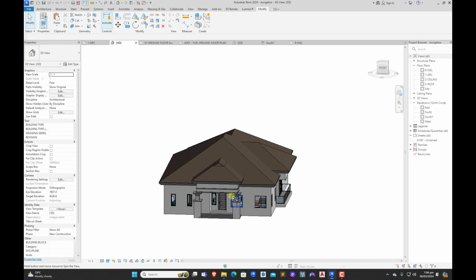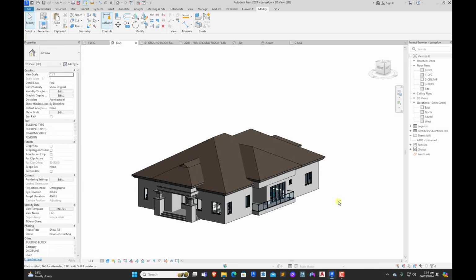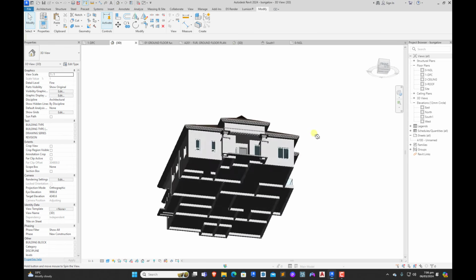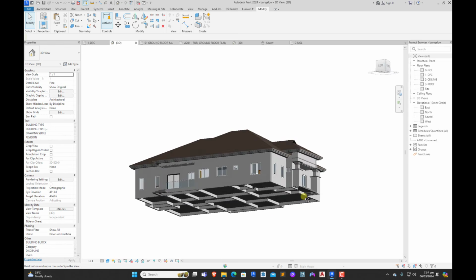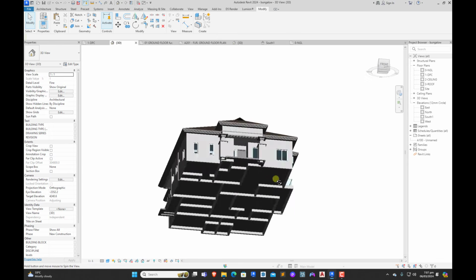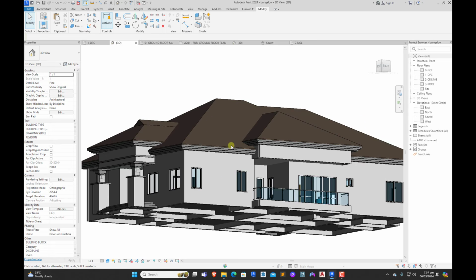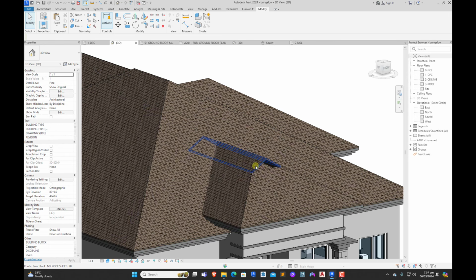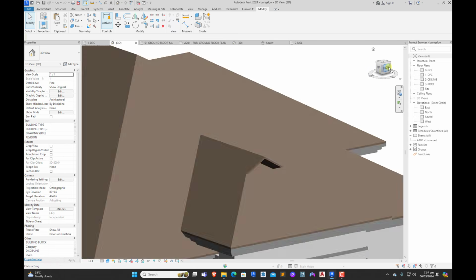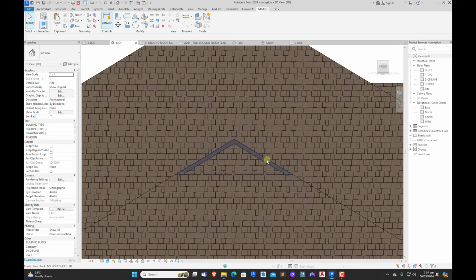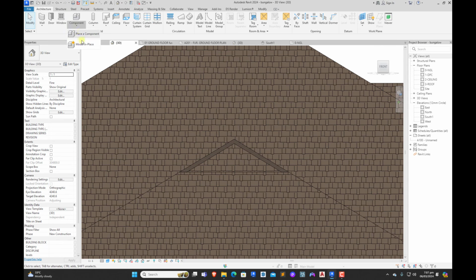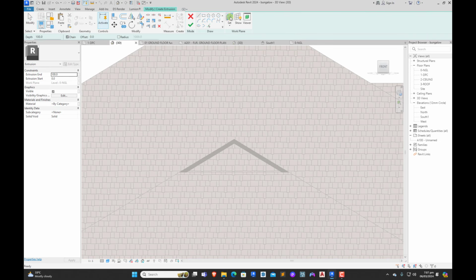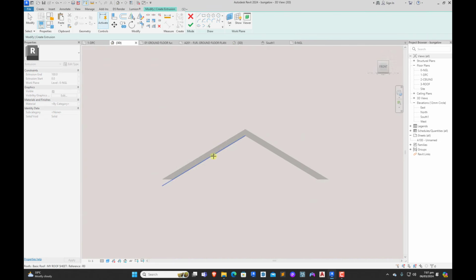Then we need to focus and do more on the facade treatment. Make this building look aesthetically pleasing, so that you can use it as a proposal and to attract people. Okay, now for us to go, now remember we're going to place something. I'm going to use extrusion to cover that area. So for that, we click on our front view. We come under components, model in place, casework. Okay, then we use extrusion. We set and pick a plane.